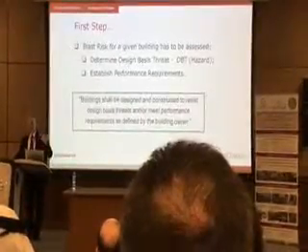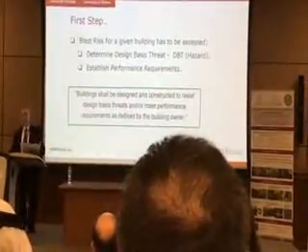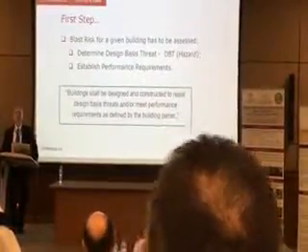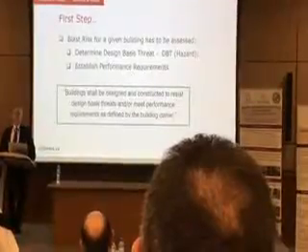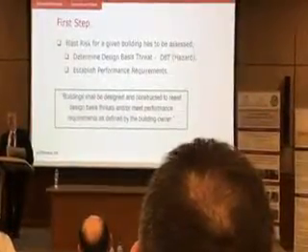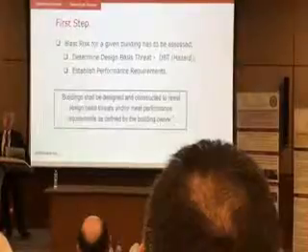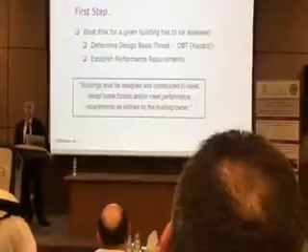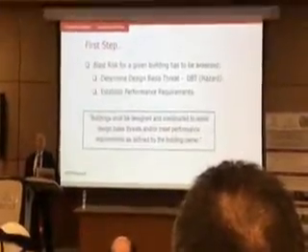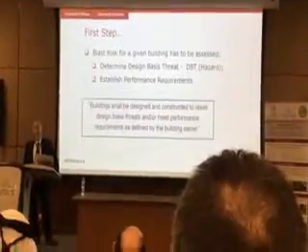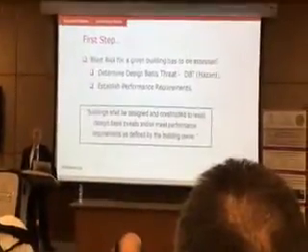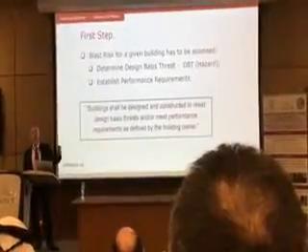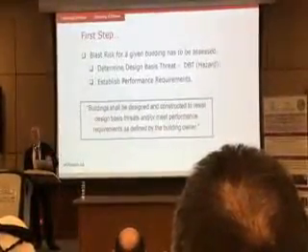First step is to, again, go outside of our typical expertise and define threat. So in earthquake engineering, what do we do? We go to seismologists and they give us ground motions, right? As structural engineers or civil engineers, we don't know how to get ground motions. They develop them, they give them as tools. Building codes specify spectral accelerations. And those spectral accelerations were developed by seismologists. And then we take maximum spectral acceleration, design our building.